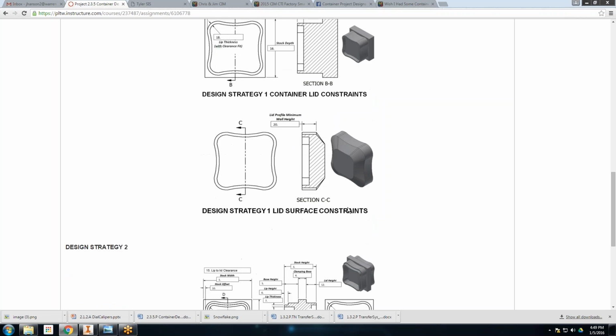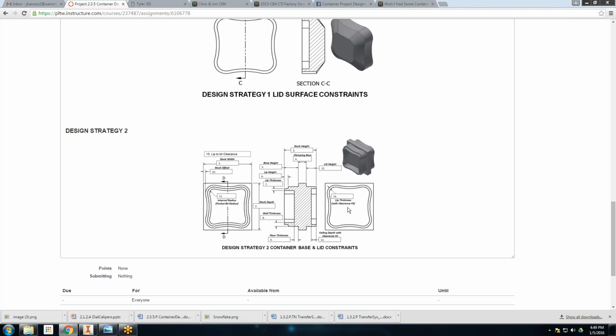The way the majority of us are doing it now, to save material, is more like this. We've got the base on one side, the lid on the other side, and a boss in between that the vise can hold on to. Once it's machined, we can split it in half on the bandsaw, and then use a custom fixture to hold it to do whatever we want on the top, whether it's a simple facing operation and then an engrave, or a face and a pocket.